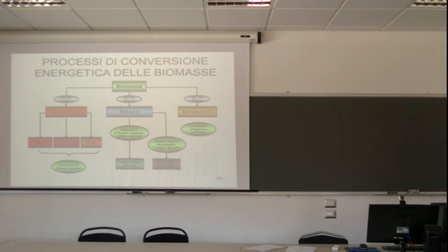We compared 316, T22 and all of these variants, regular stainless steel, the austenitic steel. There are a few which performed really well at high temperatures, but their performance was bad at low temperature, around 200 degrees Celsius. So that gave me an idea. It's the salt effect, mostly the salt and the migration effect of elements, and that affects a lot. Some of the SEM images showed that some of the materials perform better at higher temperatures than lower.